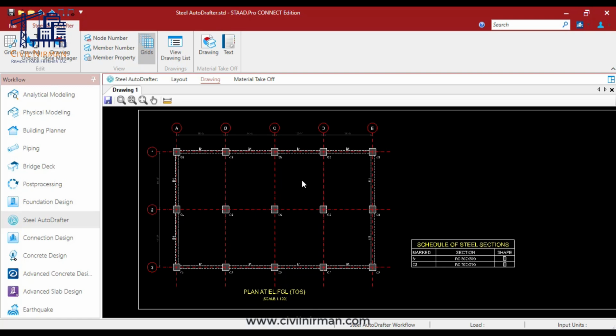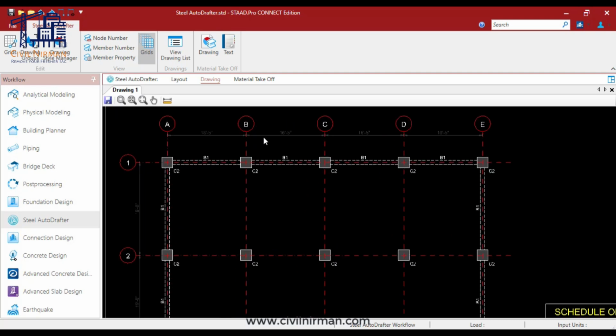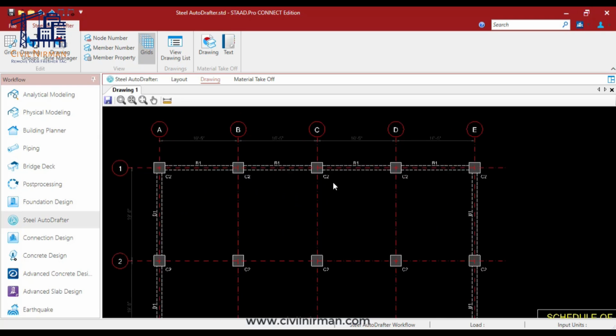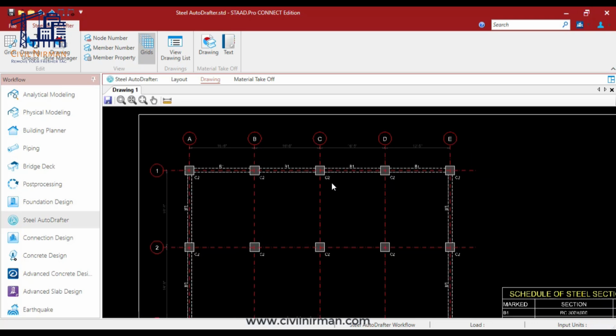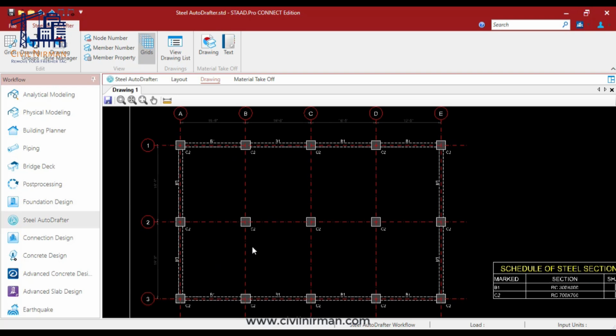It will be very helpful for you to give this particular input to your designer or a draftsman who is preparing your structural drawings for the steel or the RCC member, right? Every grid with dimension, with label, it has specified. Now why I was saying this, because every consultancy or industrial company has their own practice, and based on that they provide names and labels. But in order to generate quick drawings, or to prepare a quick input as a structural engineer, this will be very helpful to you.